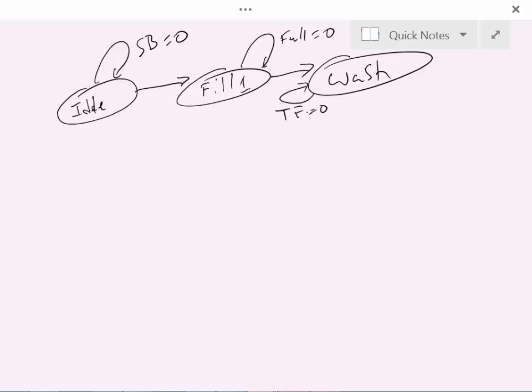But TE is a function that we would generate, that tells it how long we want to stay in a particular state. It's a variable that we would keep checking. We would use our timer to decrement our time. In other words, we tell it how many seconds we want to be in there, set up a half-second delay, load it with twice that, and every half second we subtract 1 from the number of half seconds.